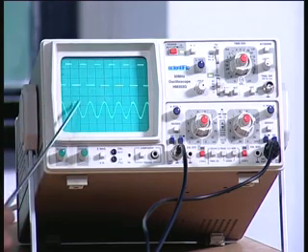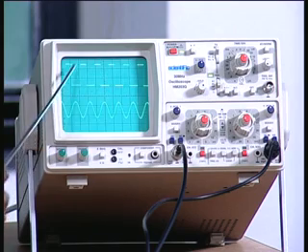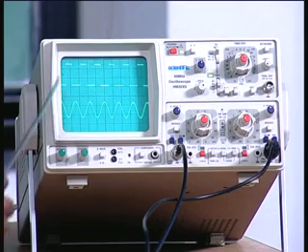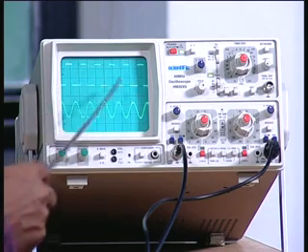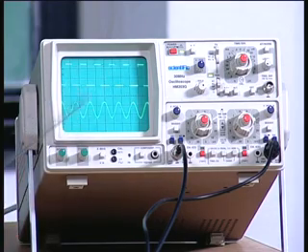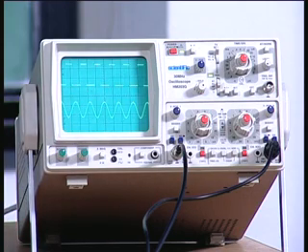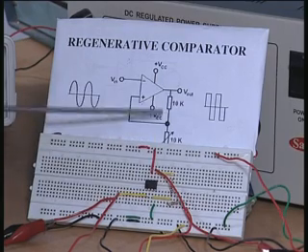These transitions occur at two different reference points now, exactly similar to what we saw in the earlier case. In the earlier demonstration also we used a sine wave and we got a square wave, but the square wave transitions were happening at plus or minus 150 microvolt. Now it is happening at plus or minus some other voltage, and that voltage is decided by the potential divider that you see in the circuit.